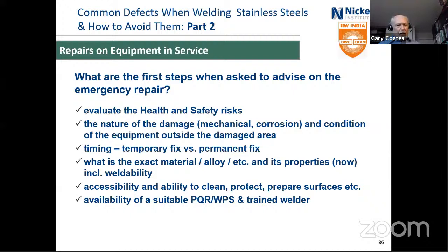If you're doing weld repair on a tank or a pipe that has contained flammable or explosive or poisonous material, you really want to check off first before you send a welder anywhere near that area. Also get the health and safety people involved, let them check off that it is fine.